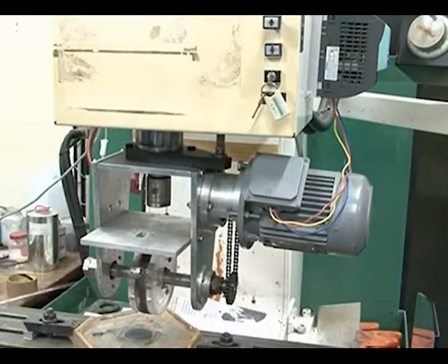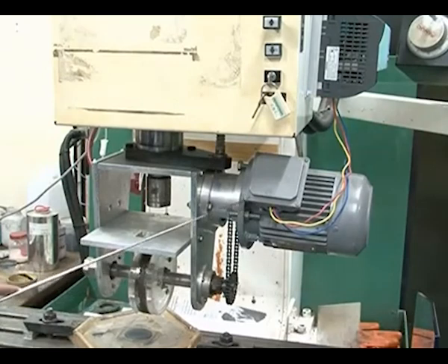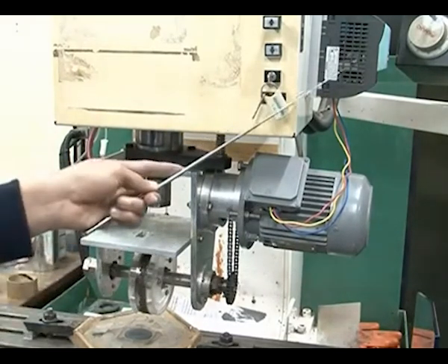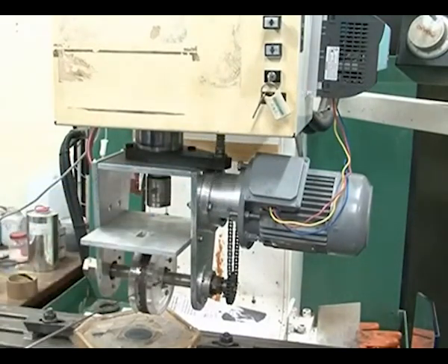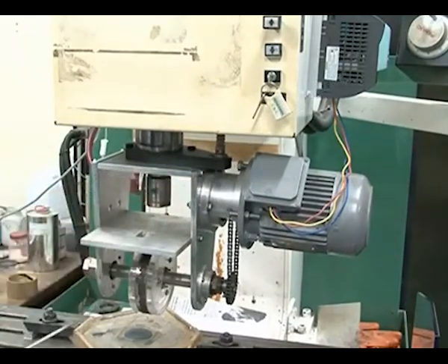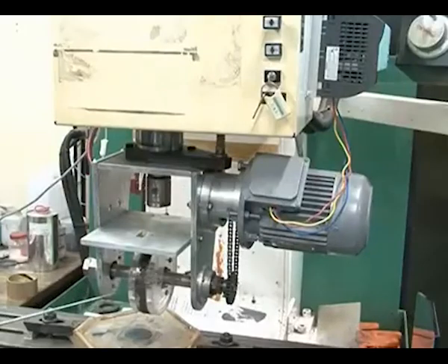This is a permanent magnet which is covered by 2 perspex sheets, and this whole assembly is called the carrier wheel. The carrier wheel is connected to the AC motor through this timing chain, and this AC motor is again connected to the variable frequency drive so that the wheel speed can be controlled automatically. Even you can give a particular value of the wheel speed so that it rotates at that particular value only. It is also required that most of the components should be non-magnetic so that the magnetic field lines should not be distracted by these components.